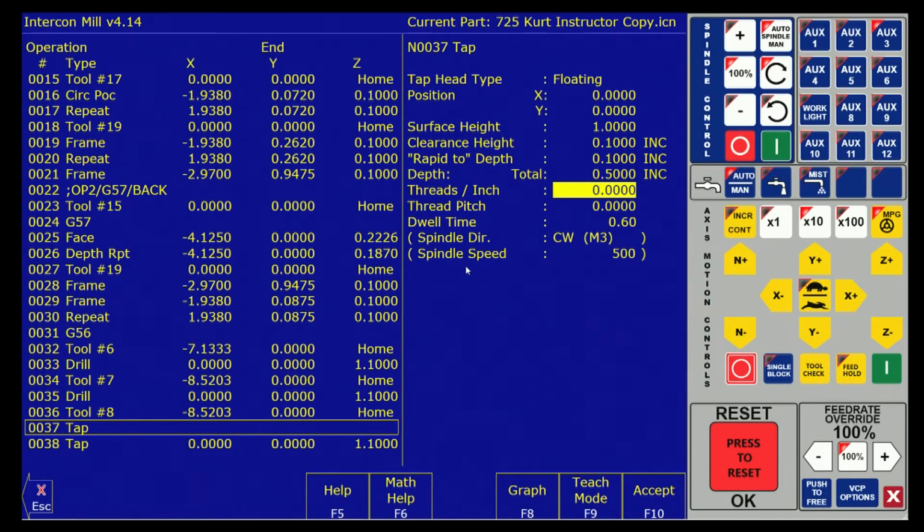So now I need to program the feed of this toolpath. And I program the feed with threads per inch or thread pitch. Why do they put both of those questions there for me? Matter of fact, what is our threads per inch, boys? 20. I put 20 and look, pitch went to 50. Man, don't you love computers? But why do they have both of those there? Head scratcher. Anybody? Make it easier, you plug in one and it'll...